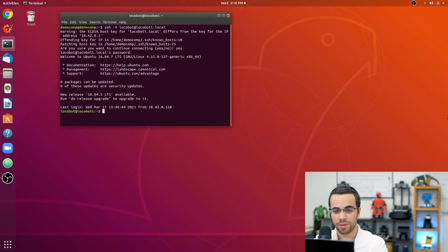Now let's start up the perception launch file by typing roslaunch interbotix_xslocobot_perception xslocobot_perception.launch robot_model:=locobot_wx200. I'm using a LoCoBot platform with a WidowX 200 arm, but if you're using a different model of LoCoBot, you should put the model name over there.